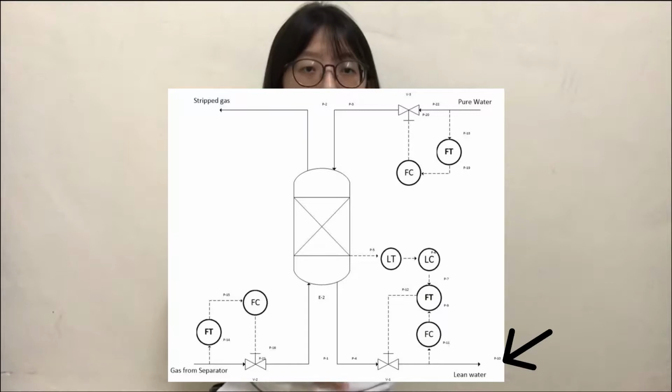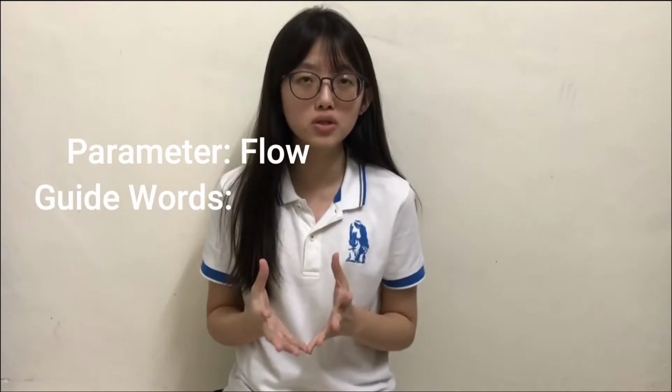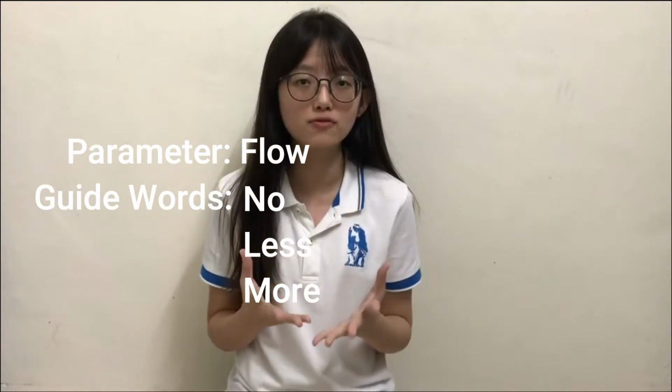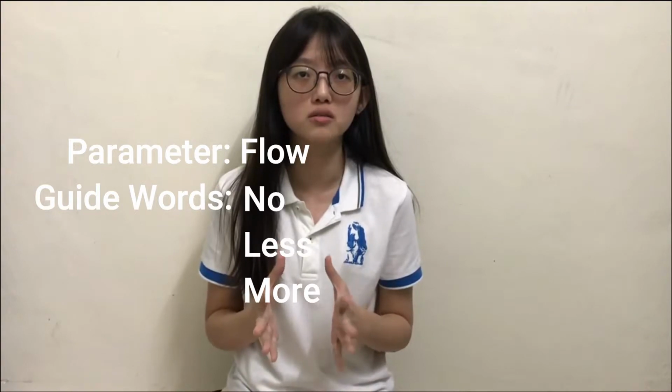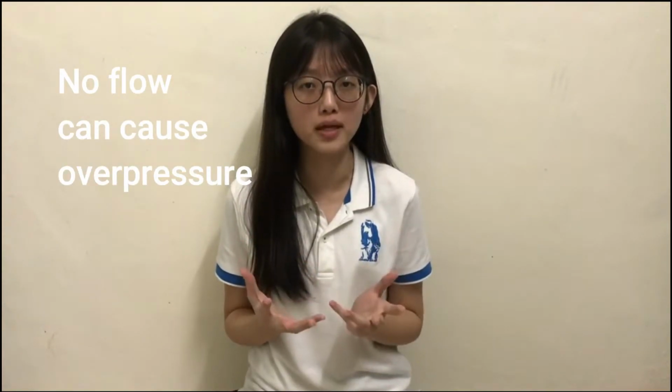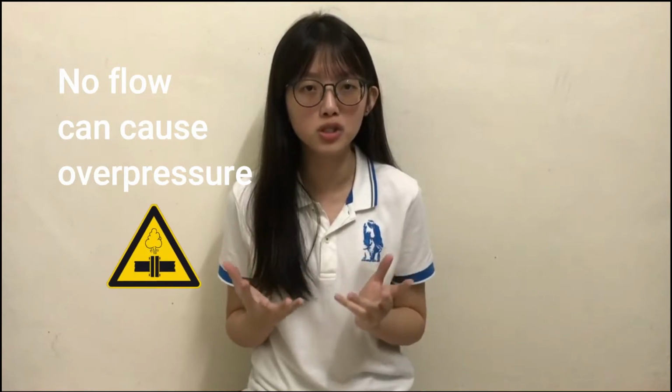The 4 streams are the feed gas line, the solvent line, the strip gas line, and the lean water line. The parameter studied for the 4 streamlines is flow, and the guide words used are no, less and more, which means no flow, less flow and more flow for deviation. When there is no flow, one of the possible causes is a blockage in the pipeline. No flow can cause consequences like overpressure in the pipeline, which leads to pipeline rupture or explosion.